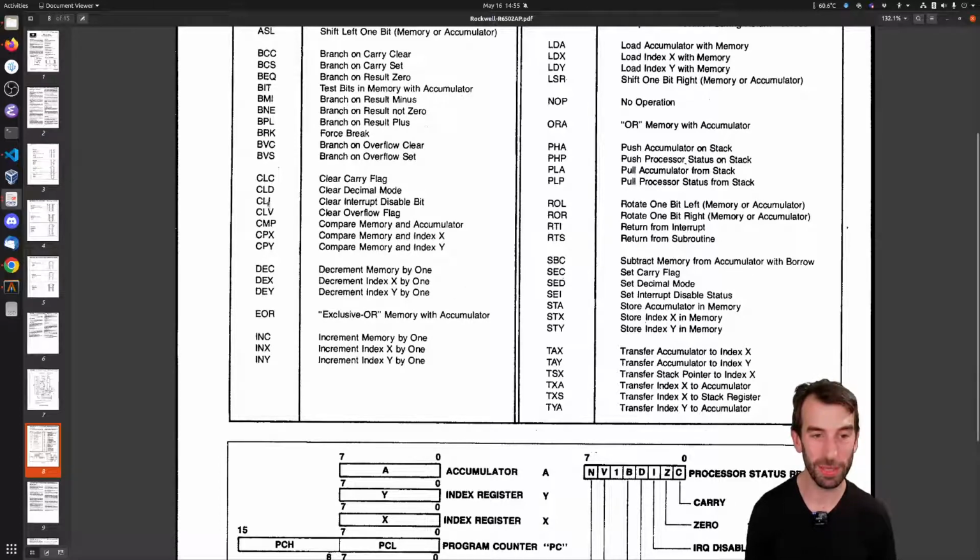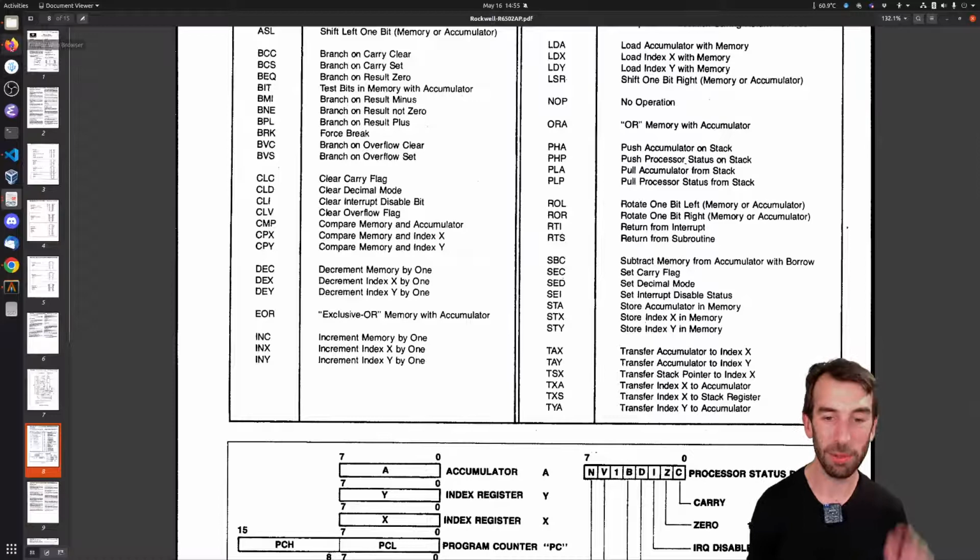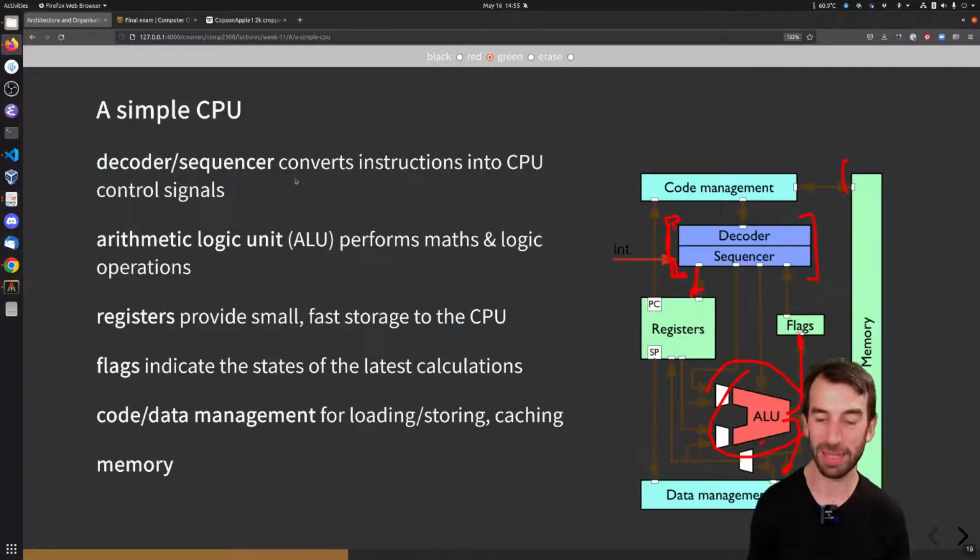And you can also do one cool thing, which is go into decimal mode, which allows you to do calculations as if we're talking about decimal numbers. So it just takes each, of the 8 bits of the data bus, the lower 4 is the lower digit up to 9, and the upper 4 is an upper digit up to 9. So you can calculate things up to 99 in 1 byte. Weird. Anyway, that's our 6502. I'll go back to the lecture now. We won't see 6502 for a little bit.